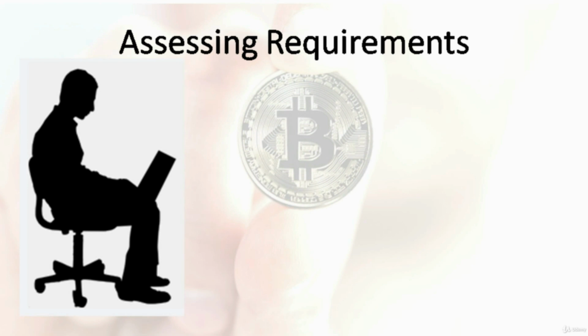You will need to consider how much power the overall facility can consume, whether you are constructing your own mining facility or just leasing a co-location space. In such a case, you can create a spreadsheet and plug in the nameplate maximum power for each component that will be in your mining facility and just sum them up. If you don't trust the specs of the nameplate to be realistic in your situation, and let's be honest, in most cases it won't, you can take real measurements with power meters of the component and multiply by the quantity that you will deploy.